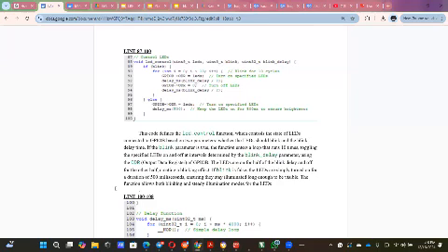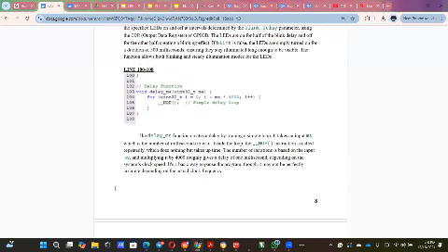creating a blinking effect. If blink is false, the LEDs are simply turned on for a duration of 500 milliseconds. This ensures they stay illuminated long enough to be visible. And then the function allows both blinking and steady illumination modes for the LEDs. Next, I will pass to my friend, Ayman.